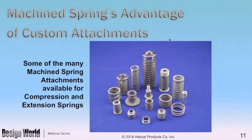As we look at the differences, here is a listing of attachments that are available on machine springs. Wire springs are pretty limited as far as attachments. So you can see threaded items here, you can see notches, you can see stepped ends, even threaded items on the ends. So all of this, anything that's machinable, well, almost anything that's machinable can be used as an attachment in a machine spring.